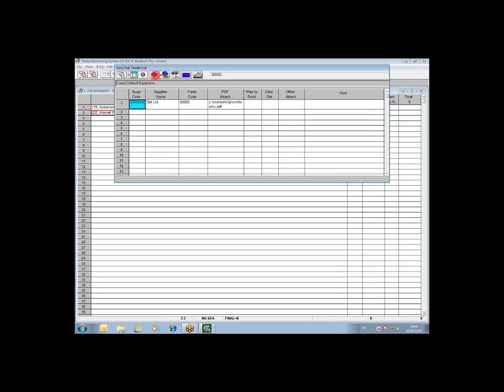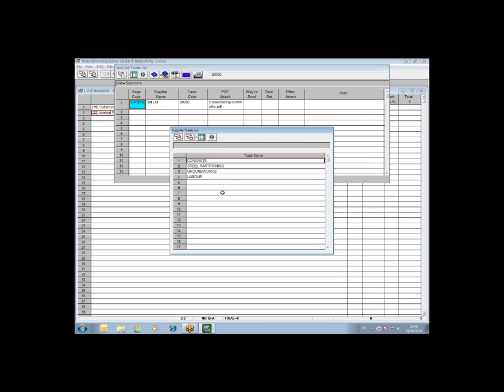It is combined. It is both used in BETS and in the subcontract comparison module. So the detail that you would set up in here will also be available to you should you have the subcontract comparison module. So what I'm going to do is just click on the View Subbies button, and you must establish this yourself. I have set up trades, concrete, steel partitioning, groundworks and labour.